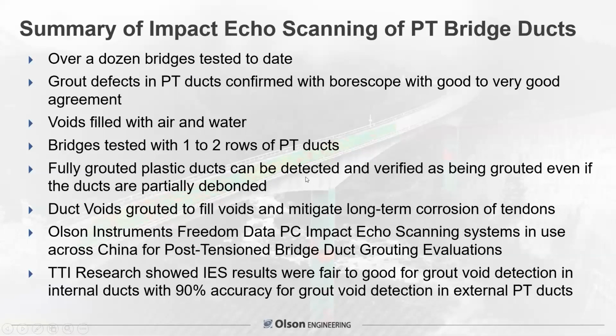The fully grouted plastic ducts can be detected and verified as being grouted, even if the ducts are partially debonded. If it's fully debonded, we have trouble with that, of course. But normally, in most of our experience, both plastic and metal ducts have been reasonably bonded. The duct voids are grouted to fill the voids afterwards by the contractors to repair it, mitigate the risk of corrosion of the tendons.